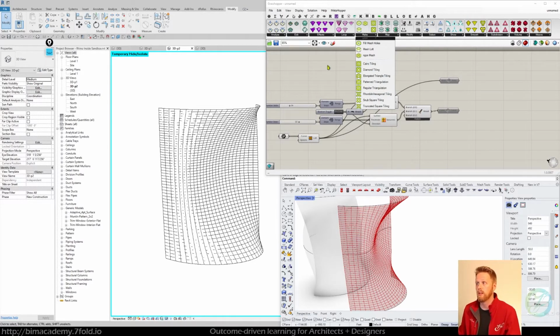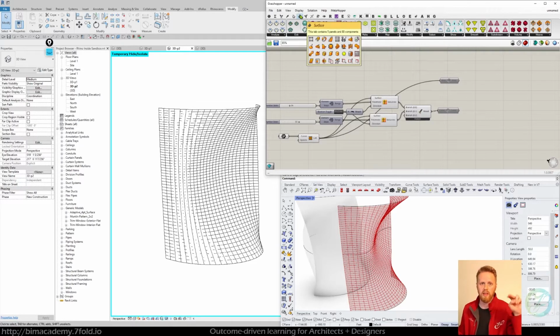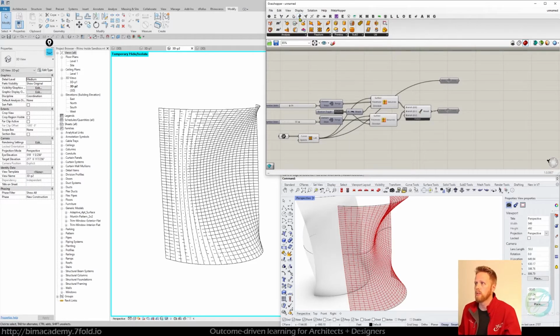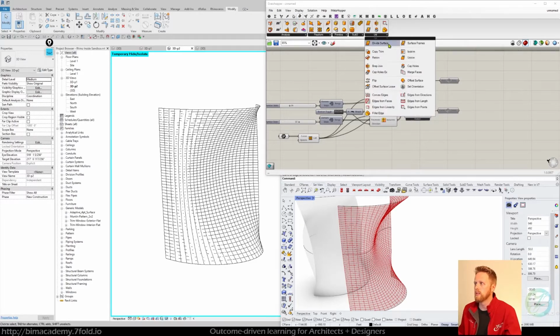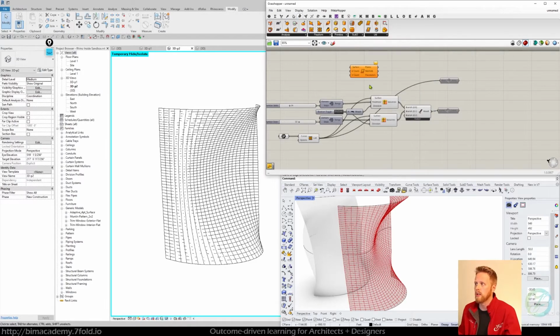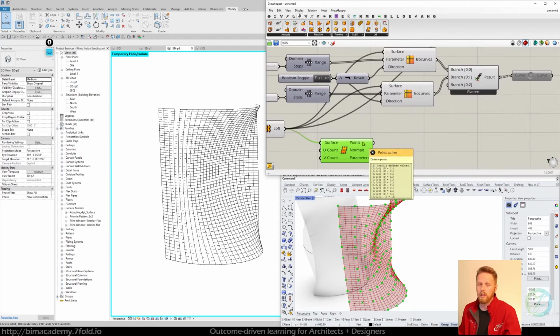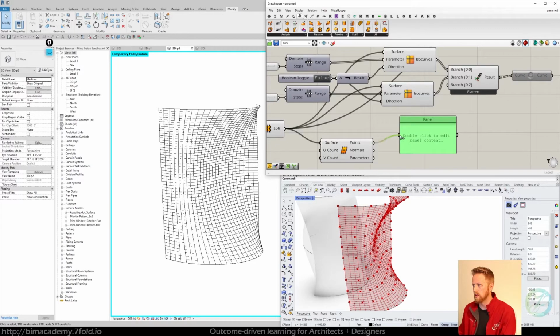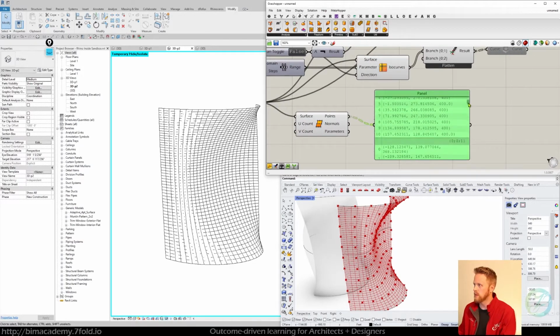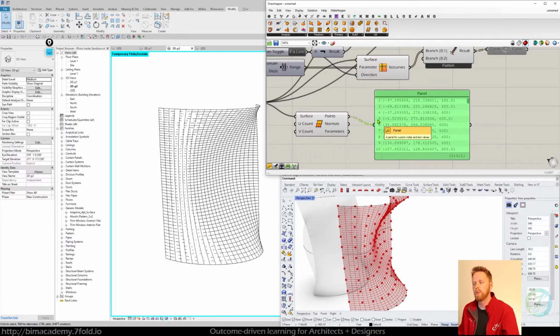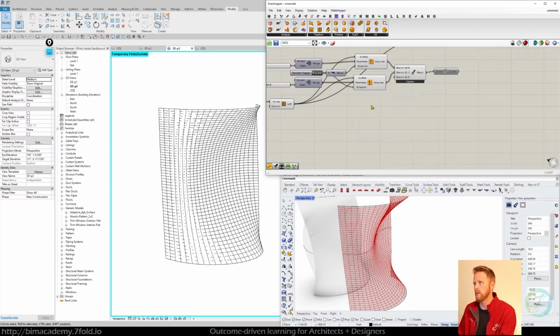Now, in the vanilla out-of-the-box Grasshopper components, you can go to the surface tab up here, go over to utilities and divide surface. The downside of this one is that you don't get the points grouping into a branch. You don't know which branch they're all on. So if I just feed these points out, you can see it's basically just organizing them by U and V, so an entire row of points. It's not knowing relative points to each cell. So use paneling tools, Lunchbox, or M+.